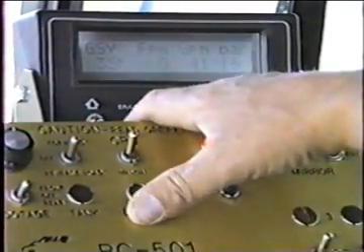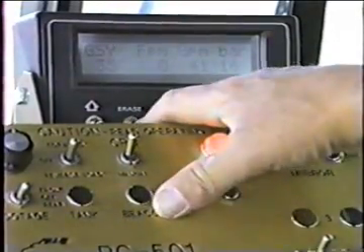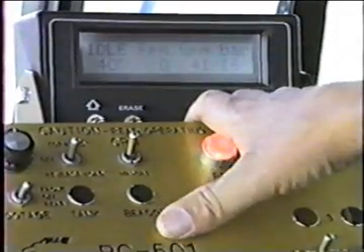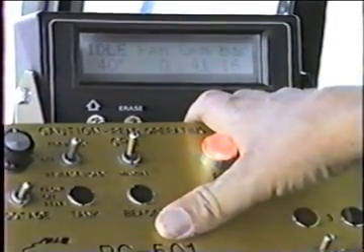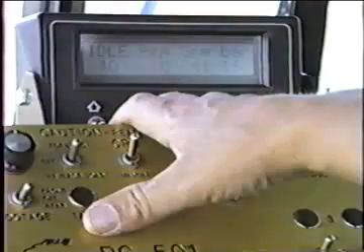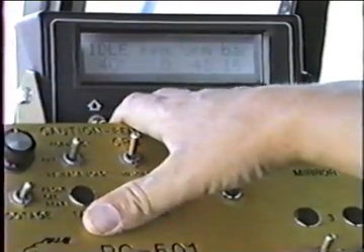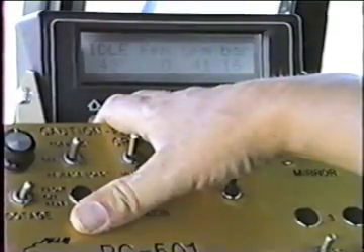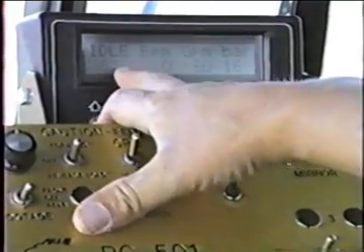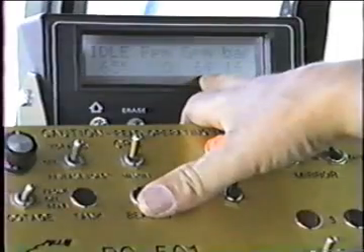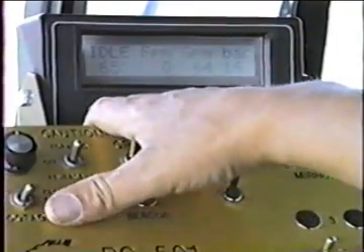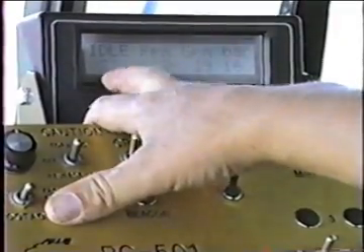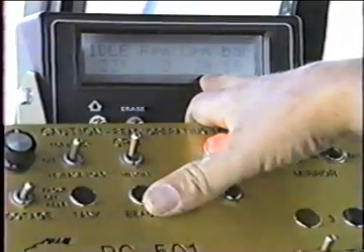We can look at that idle speed just by pushing the center switch up to the erase position. Now we read idle 40, and that's what we have the idle speed set at. Anytime the master switch is off, it'll idle at that speed. We can change that speed with the arrow switch. If we hold it up, this number comes up and you'll see the GPM actually come up over here. If we hold it down, now we can go back down. Now we've gone down to 23 here, and we'll see this come down to 23.